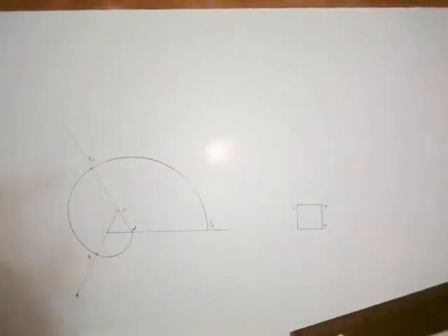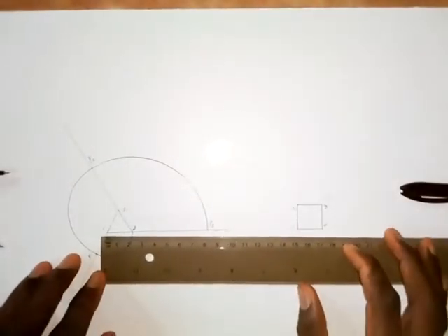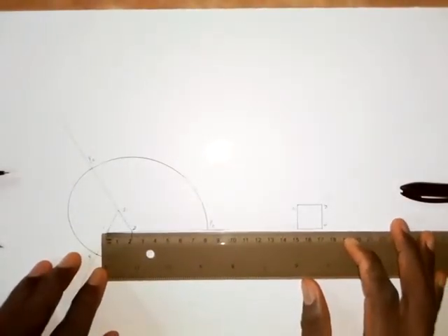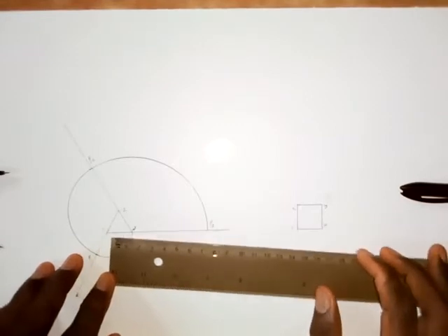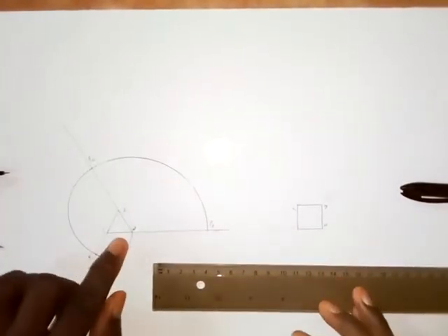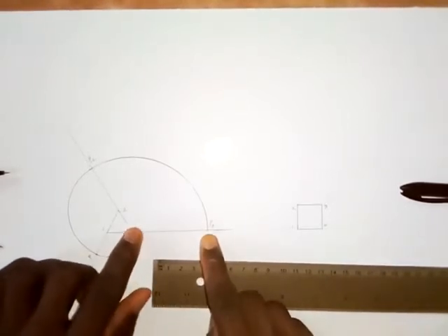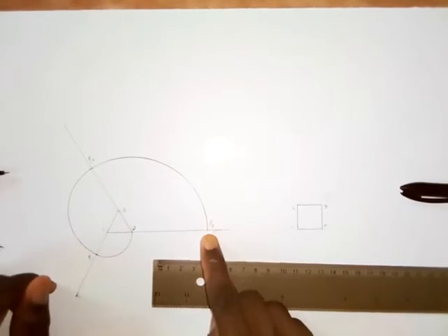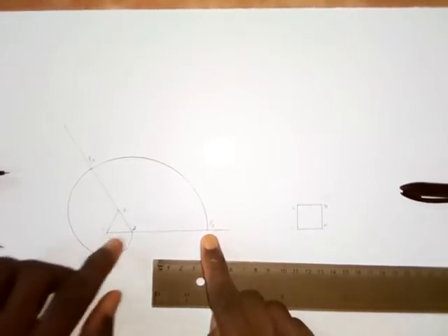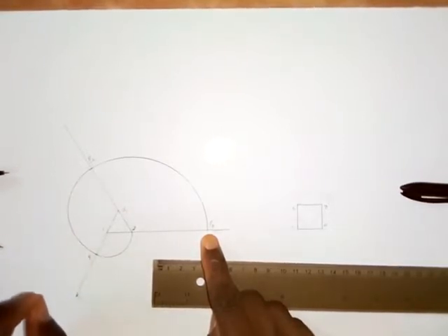The triangle has a side length of 20 mm. One thing about an involute is that when you are done, the distance from point 3 to point P3 will be equal to the perimeter of the given triangle. The perimeter of this triangle is 60 mm, as the length of the side is 20 mm.